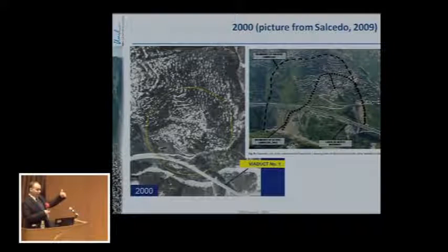You had two important things. One thing, if we had the LiDAR DEM, we were able to map in detail the former landslide. And second, with InSAR, it was possible to see the movement of the houses and to map the movement in detail.